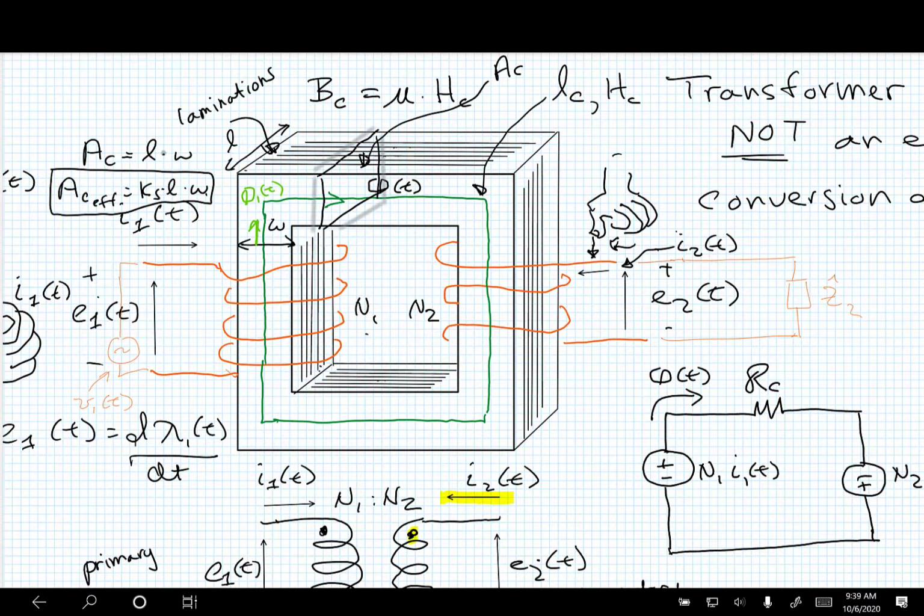If I'm running at no load, I'm going to be operating at a certain flux density. If I draw more current, do I want the core flux density to go up or down when I'm loading this thing? Just to give you guys a thought, think about magnetic structures. I'm applying it to a practical situation.